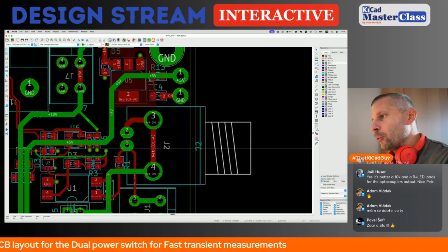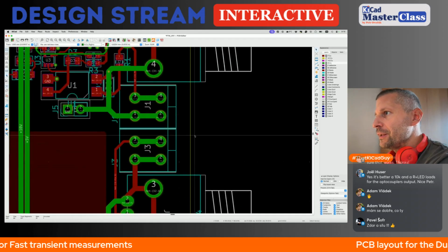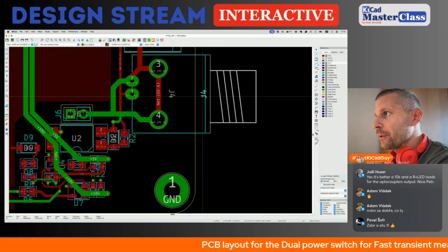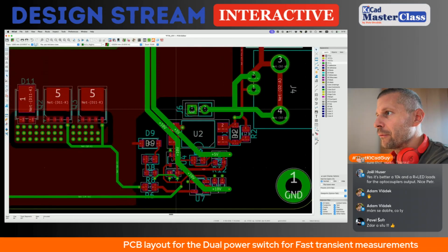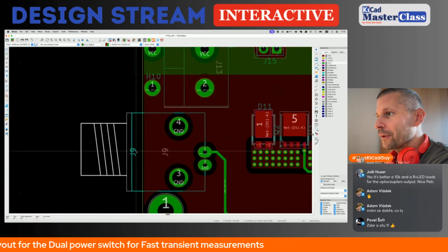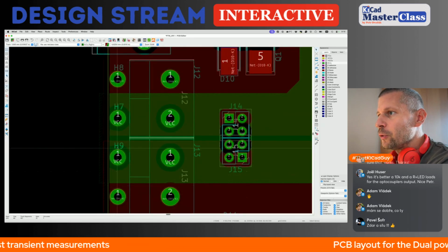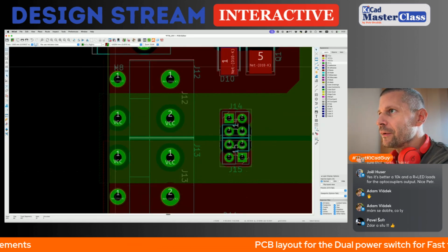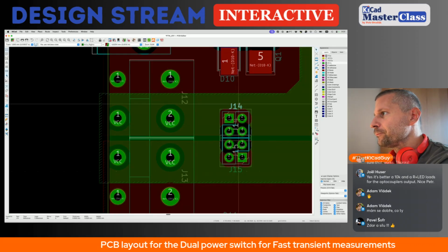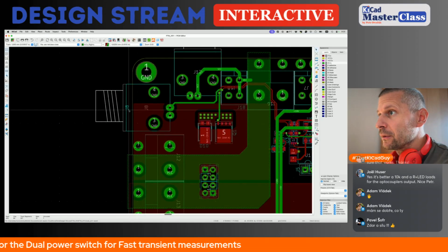I'm removing the designators for connectors because these designators are not important at all. There will be labels in the silkscreen for them. So when you need to navigate to a particular connector or jumper, you are not usually using the designator, you are looking for labels.